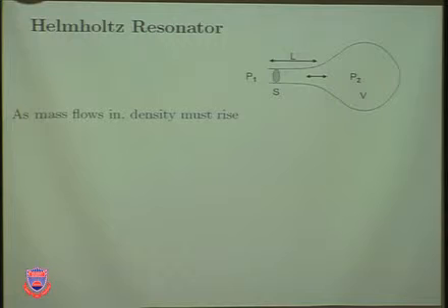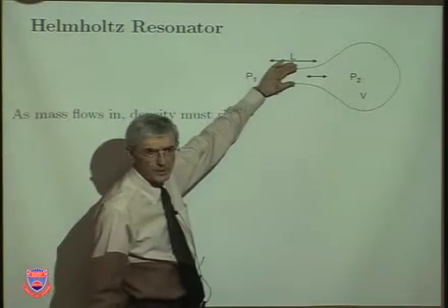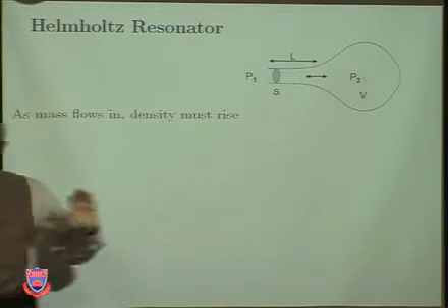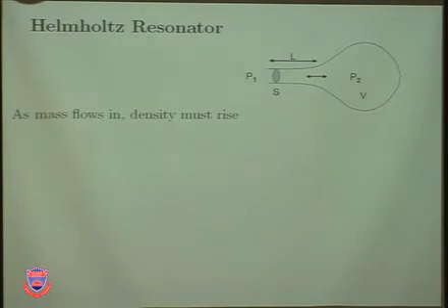Now, as you blow onto it, or wind goes through it, mass flows in. If the mass flows in, density must rise. This is another example of this is cars. When you're driving on the highway, if you open the window of the car just a little bit, that acts like this opening here, and then you can actually feel this resonance. That's a Helmholtz resonator, same concept. Or sometimes a small pinhole, then you can hear the whistling.